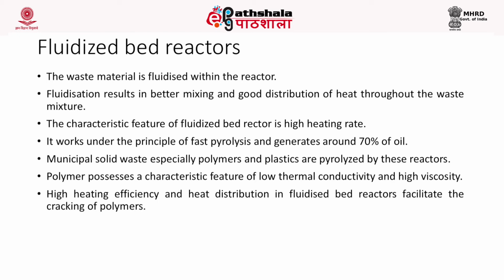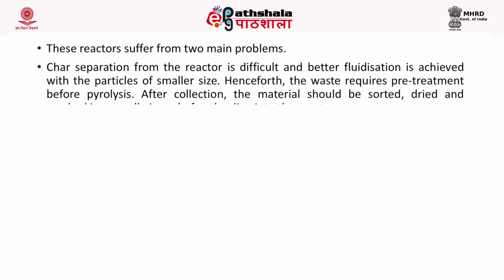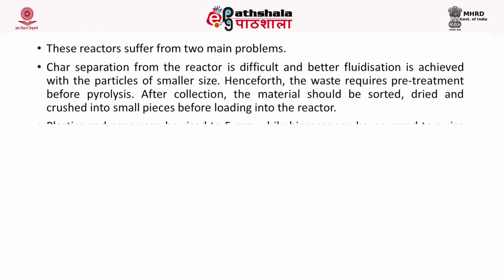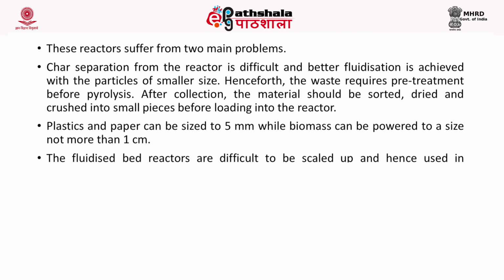Now, high heating efficiency and heat distribution in these fluidized bed reactors always facilitate the cracking of these polymers. However, these reactors suffer from two main problems. One, the char separation from the reactor is very difficult and better fluidization is achieved with the particles of smaller size.